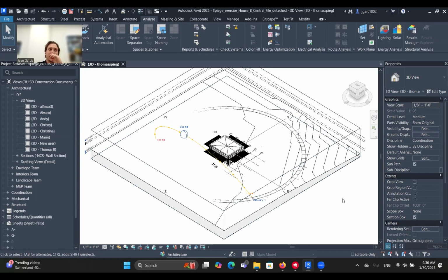Say you want to do, I don't know, a flat roof that will overhang on the southern side, because you know the most solar exposure is going to be on the south side, and then you want the slope to go towards the north side. So the lowest part of the slope will slope down to the north side, so you have the water flow there, and then you have a nice cantilevered flat roof facing the south. I don't know. It's really up to you.